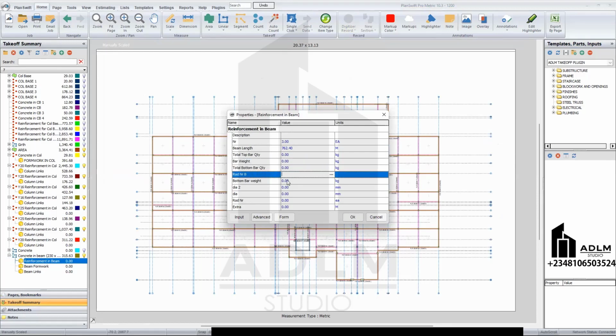From the rod number here, B is bottom. I have 2 bottom, from what I showed you earlier. Then the diameter is 20 mm down, while for the top it's 16 mm diameter, and the number on top is 2. So you have 2 up and 2 down, right?